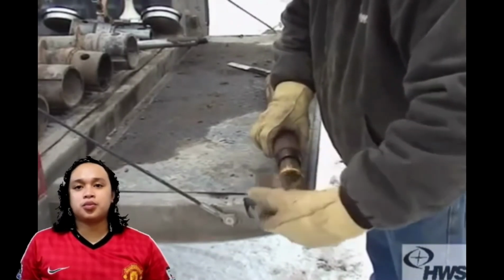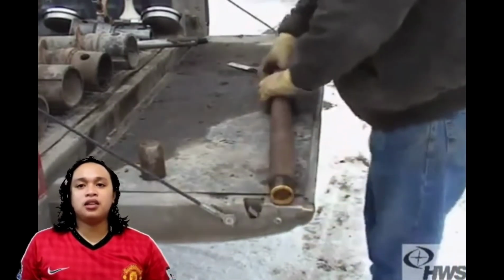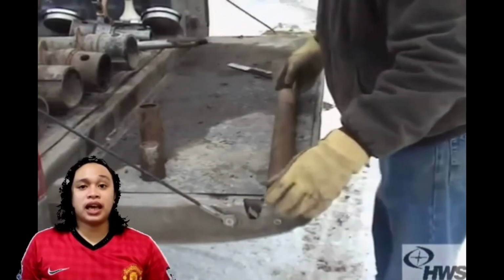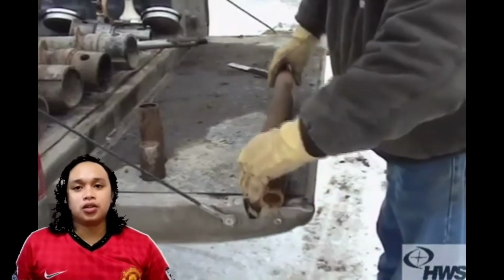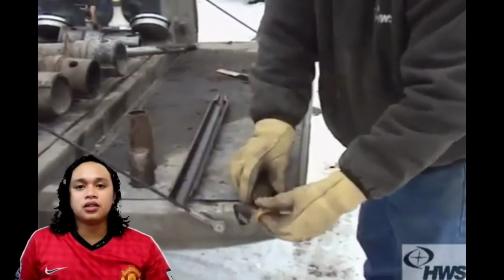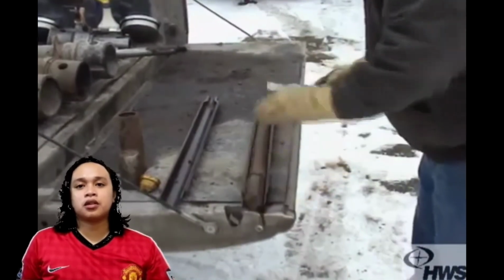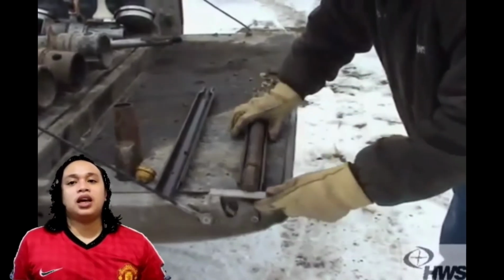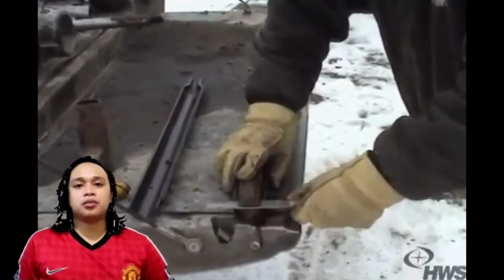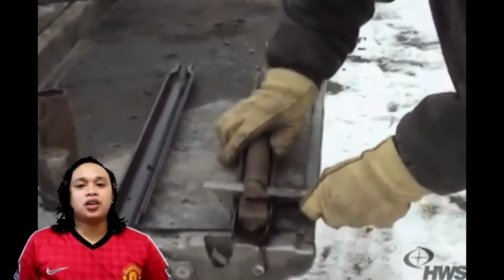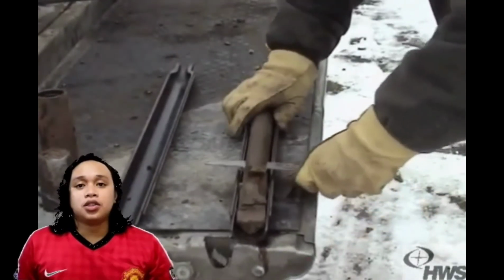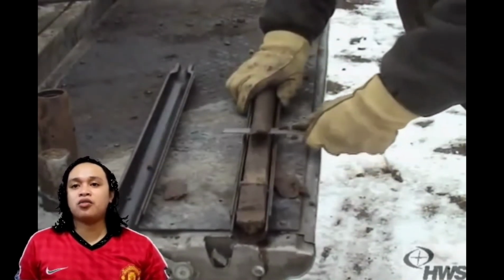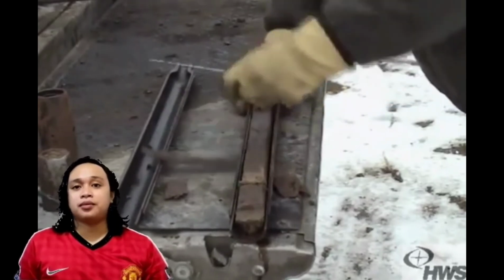Clean the split spoon sampler and apply a thin film of oil to the inside face of the sampler. Connect an A-drill extension rod to the split spoon sampler. Slip the 63.6 kilogram weight onto the guide pipe assembly and connect the guide pipe assembly to the other end of the A-drill rod. The chain connected to the driving weight is tied to the rope passing over the pulley at the tripod head.